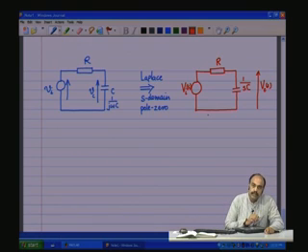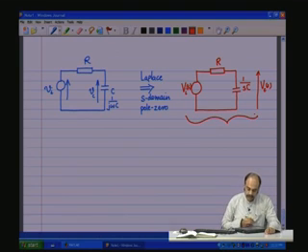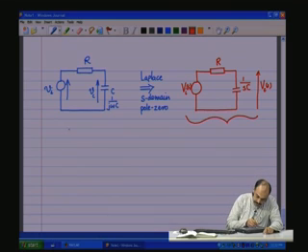Now, this is the circuit which is now transformed into the Laplace domain, and if we perform the analysis on this, we will get the transfer function. For example, if we need to know, let us say Vo or Vc, in this case Vc(S) by Vi(S).